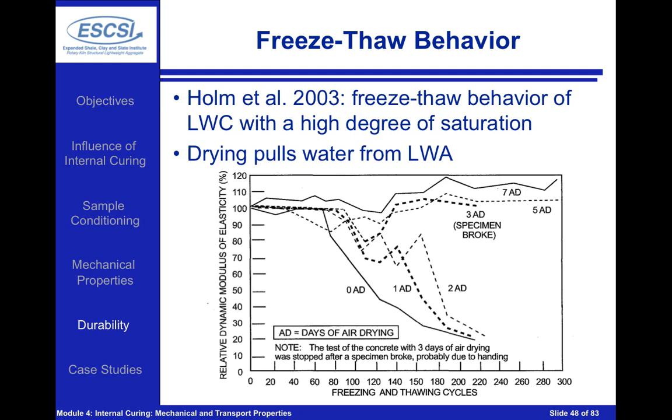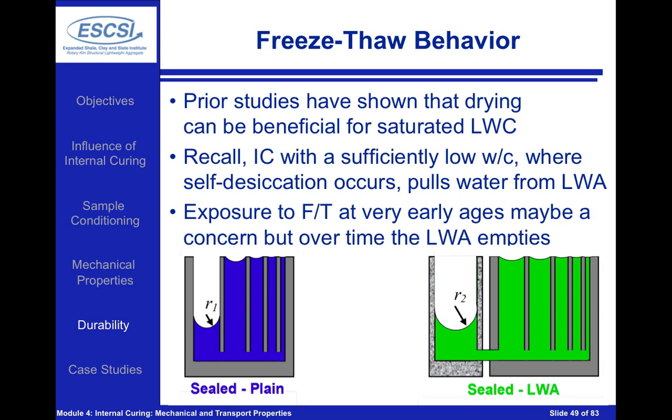In addition to looking at conductivity, Holm has looked at freeze-thaw behavior, and one of the things that we can notice here is that if we get some air drying into conventional lightweight aggregate concretes, we'll typically see that they behave much better. The whole reason for this is the drying will pull the water out of the lightweight aggregate, out of those big pores, and get it into the paste, and then it becomes very difficult to resaturate those pores over time. So the prior studies have shown that drying is beneficial.